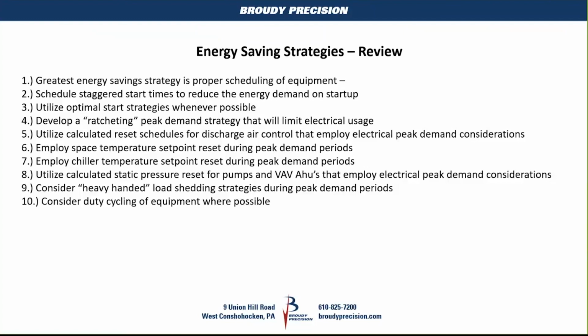Do the same thing with chilled water. When we're in a high demand situation, instead of making 42 or 44 degree water on our chiller, we reset that water temperature upwards, and our chillers unload, and we start using less energy that way.